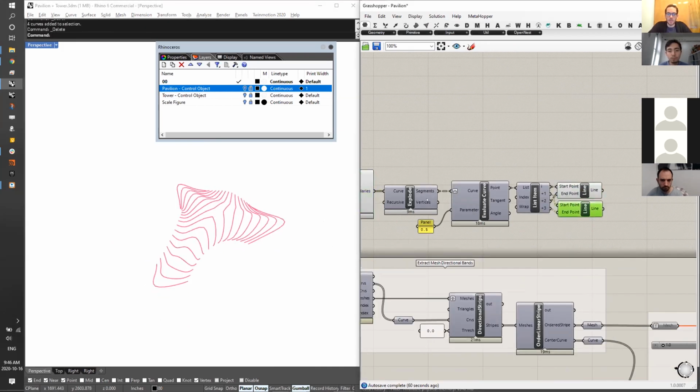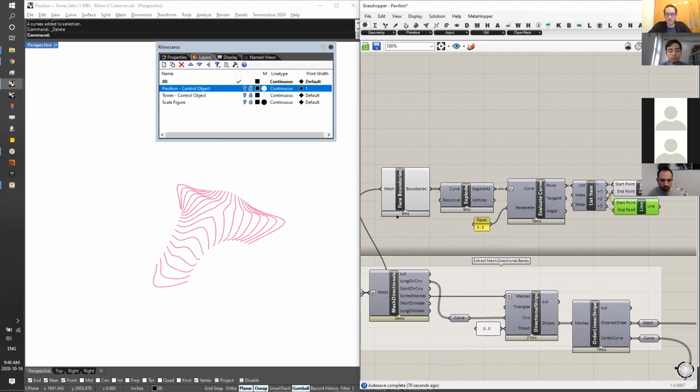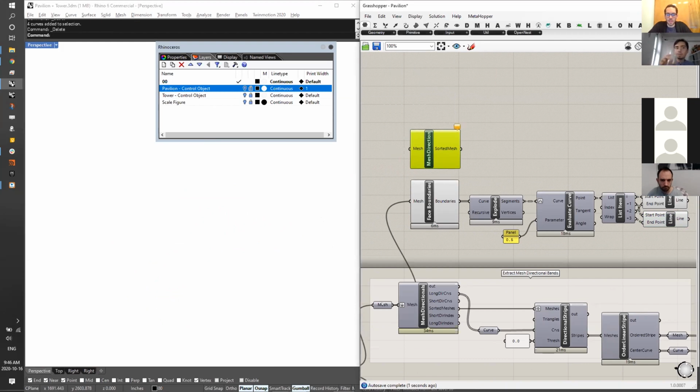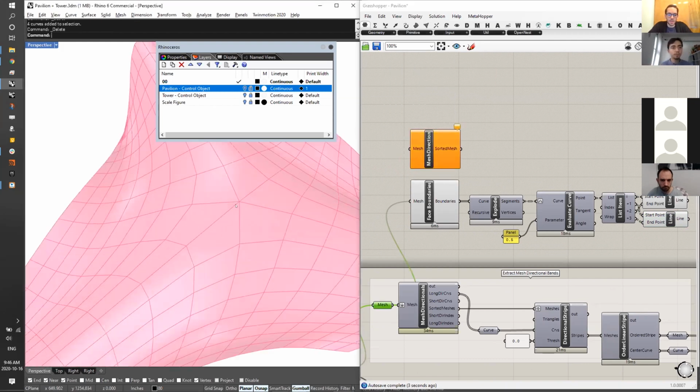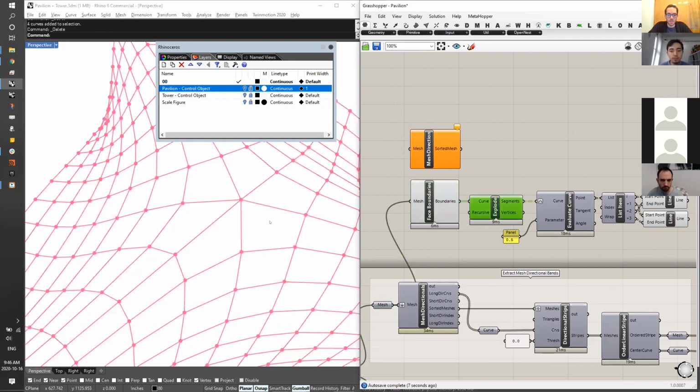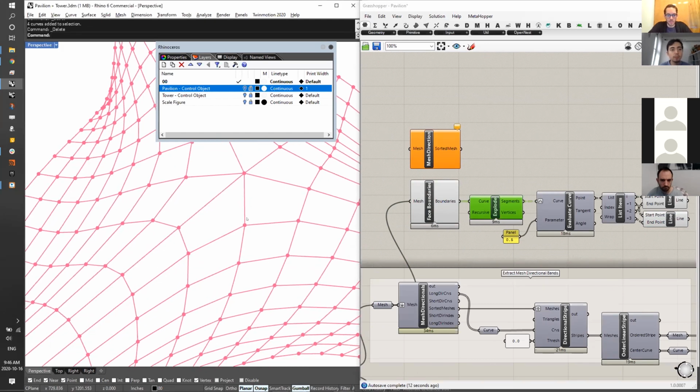Now, if you have a mesh that's not ordered, which can happen, one thing that will solve this is called mesh direction. Mesh direction will take a particular mesh object and try to order all the faces. If you think of the order as the points, it tries to order them so they're all going a certain direction, I think clockwise, for example.